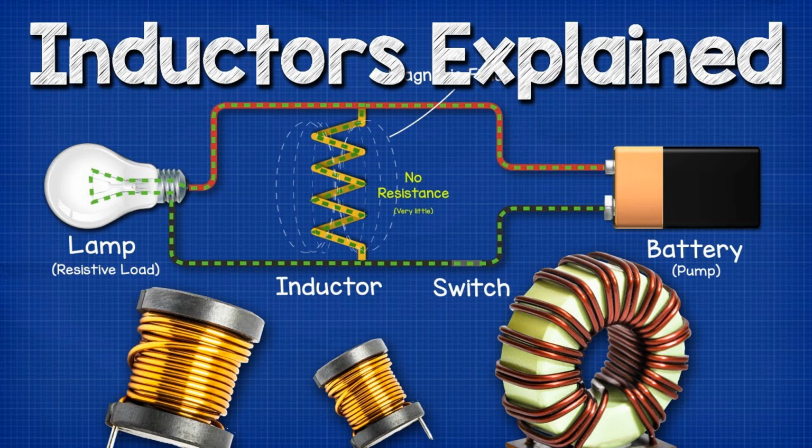Application. Audio transformers are used in audio systems to transfer signals between different stages of the circuit, matching impedances and isolating sections of the system. They help in maintaining signal integrity and reducing noise. Example: audio transformers are used in professional audio equipment, such as microphones and amplifiers, to isolate and transfer audio signals without introducing noise or distortion.